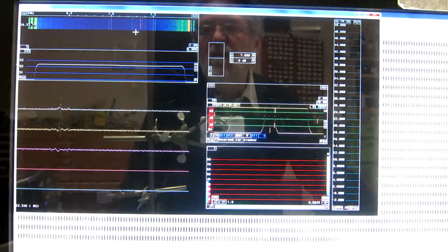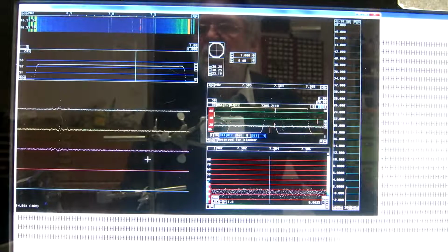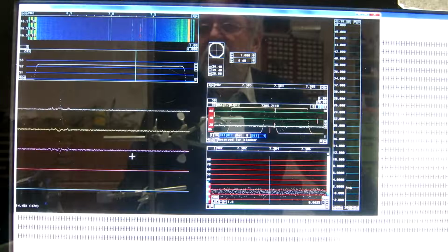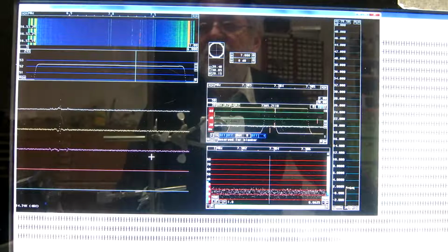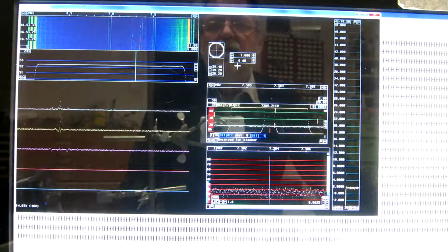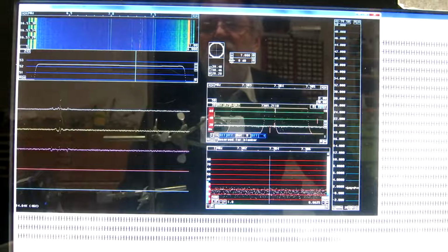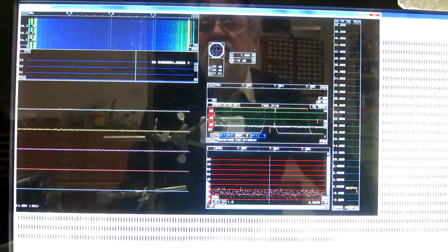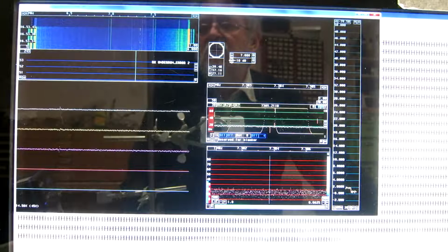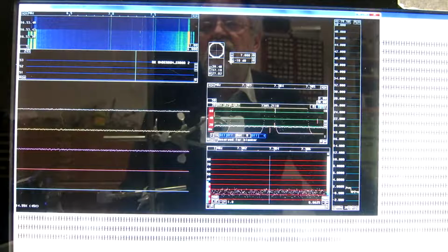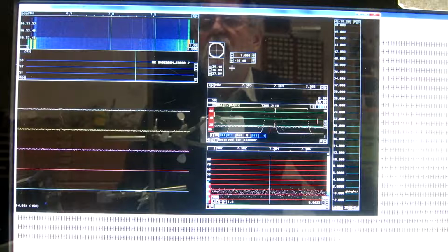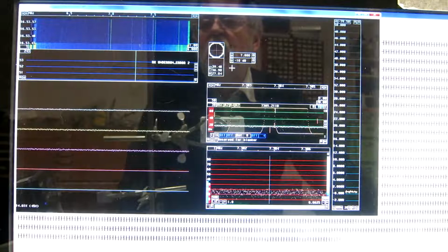And click somewhere. And I don't remember exactly how it looked, but when it is on the video I can go back. I think it should be a little bit better now. I can switch in the attenuator, and the calibration is still good. The impedance change doesn't matter much now that the pulses come from a proper 50 ohm source.